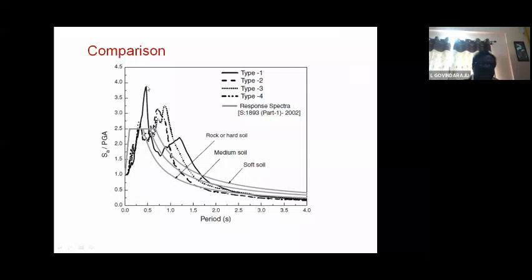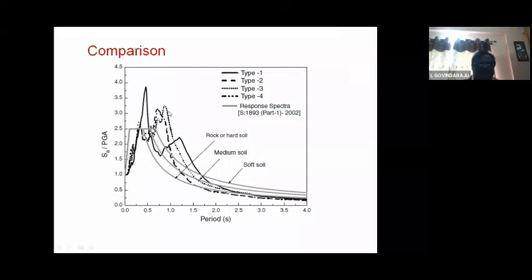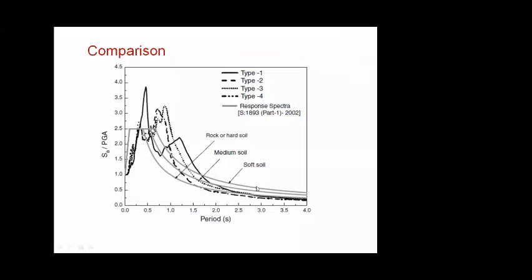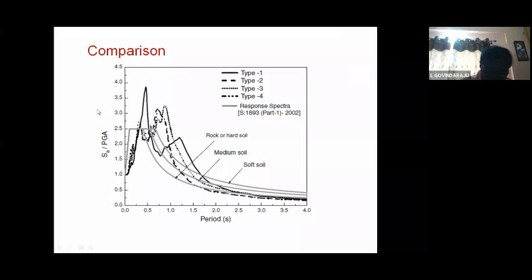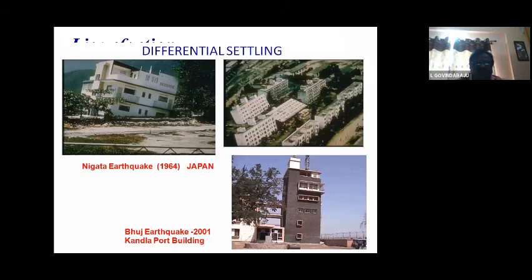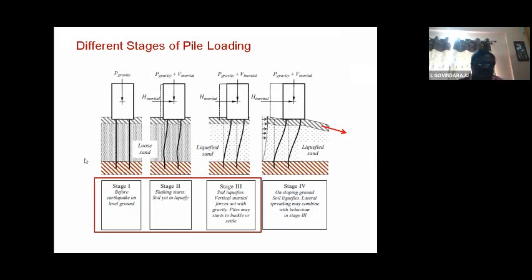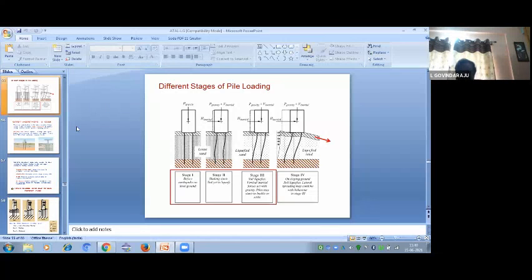But from our analysis, we found that the spectral accelerations are still high. So what we can conclude from this is that site-specific ground response studies are very much required to revise our codal spectra, which will enable our structural engineers to go for proper earthquake-resistant design of structures by adopting such realistic response spectra curves. I have one more presentation, but due to time constraints I will stop at this point, and I wish to interact with you on some other occasion.